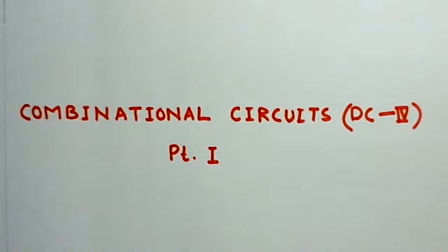A 2-bit by 2-bit parallel multiplier circuit is illustrated to bring about the hardware needed for the circuit. AND and multiply truth table are identical, so product term generated by AND and sum using adder or XOR gate.